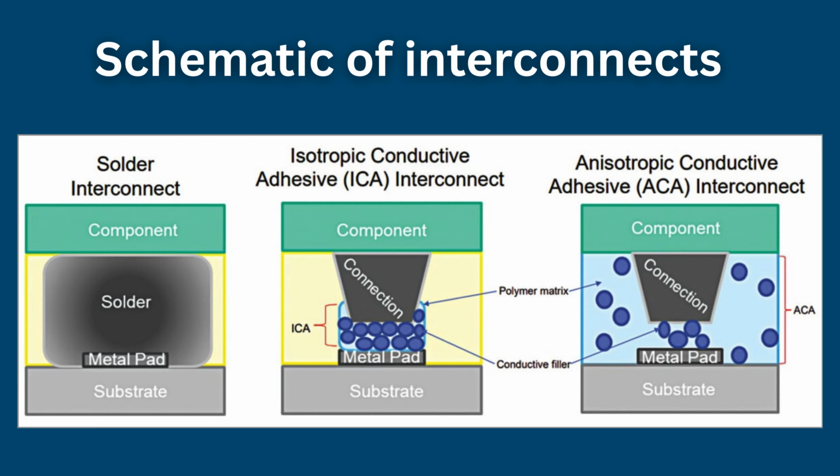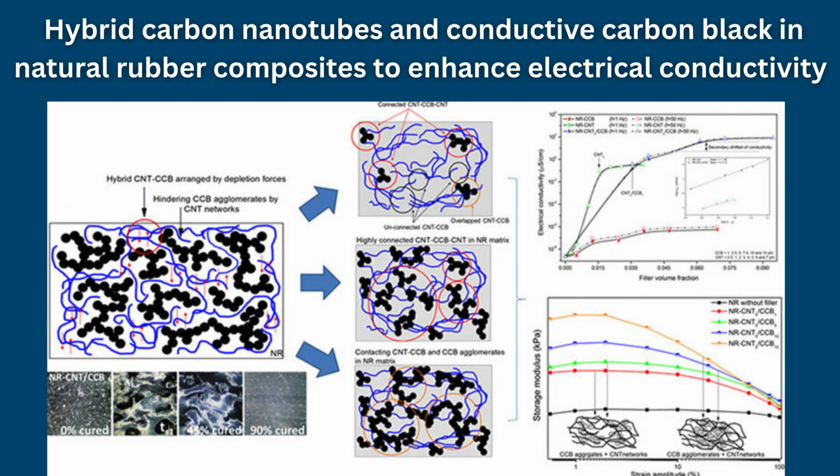Silver microfillers such as flakes, 3 to 10 micrometers, and microparticles, 2 to 3 micrometers, are often incorporated into polymer matrices such as epoxy or polyurethane. During curing, partial sintering of silver particles may occur, forming conductive microstructures that improve electrical conductivity. Polyurethane-based ECAs containing such fillers can achieve resistivities below 10 microohm-cm after curing at approximately 150 degrees Celsius.